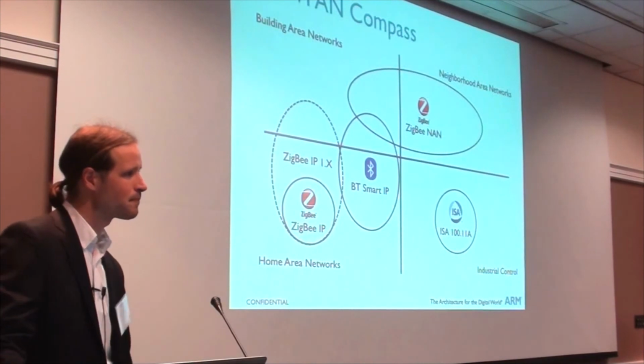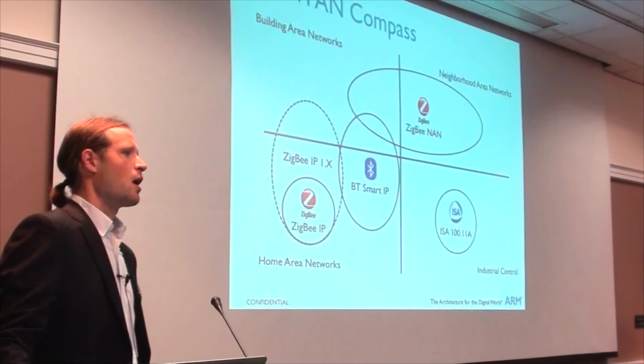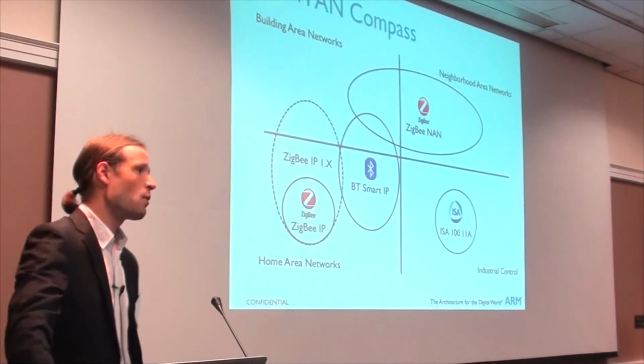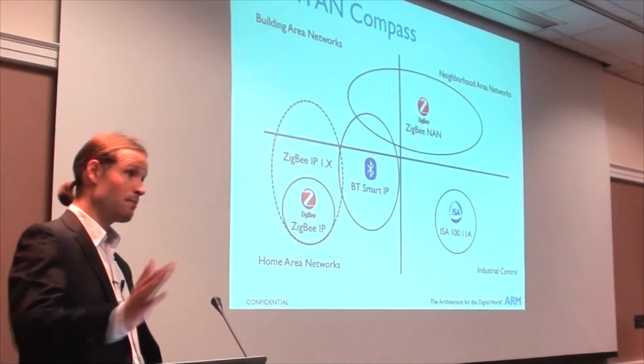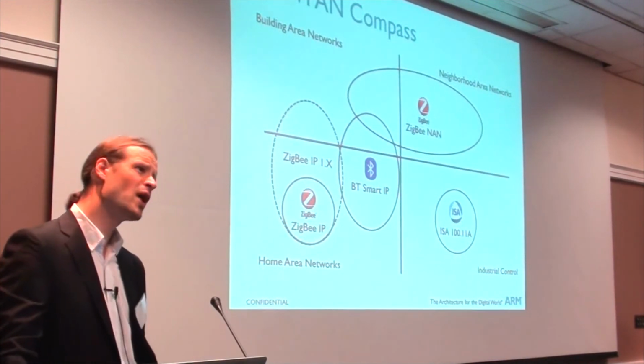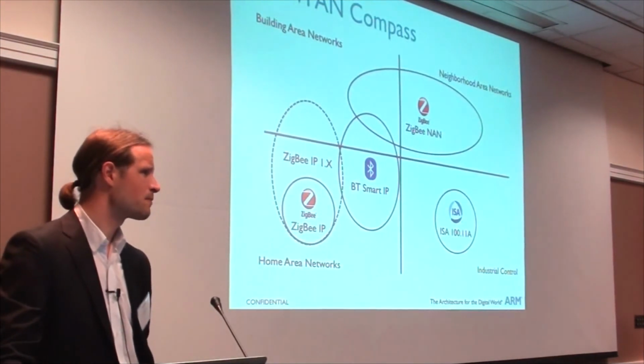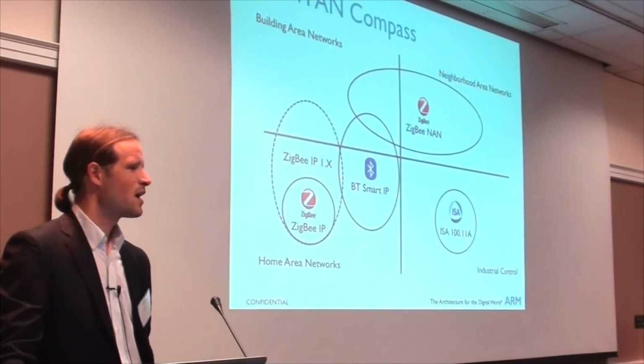I think you're right, the problem is the hardware. There's a lot of 2.4 gigahertz hardware out there. There's not nearly as much selection today in the sub-gig area, but we're seeing more though. Like Atmel recently released a great sub-gig part. I think it's the 212. Yeah, I'm using the 212 a lot. It's a good chip, but I think it doesn't support the G standard.